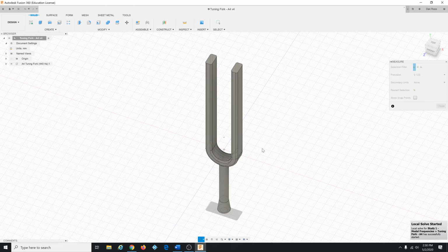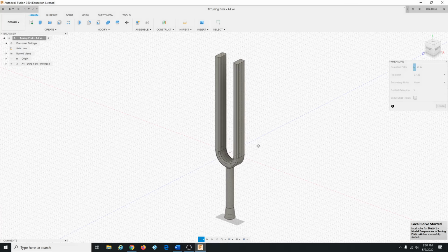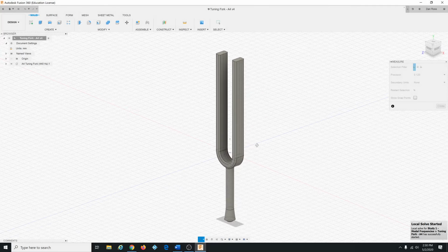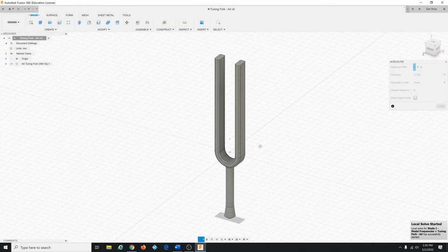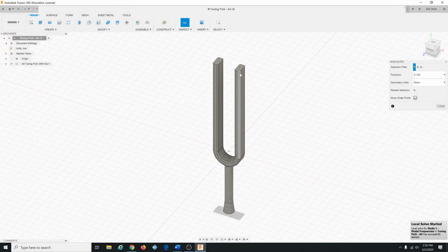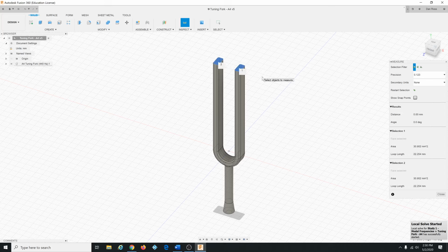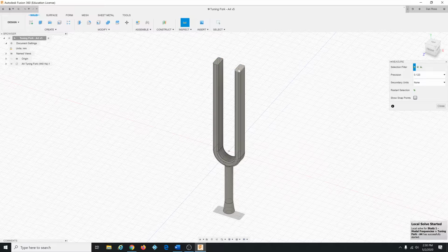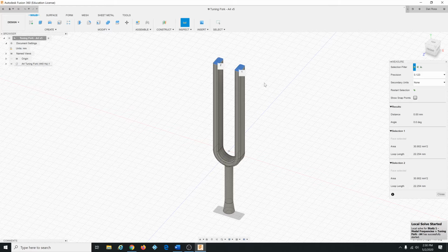All right, so this was modal vibration analysis. So a tuning fork is an obvious thing that you actually want to vibrate, but this is important for things that we don't want to vibrate, because everything has a resonant frequency. In this tuning fork, its resonant frequency is 440 hertz. But in real life, there's machinery that you often don't want to vibrate. So it's convenient or useful to solve for the resonant frequency and then check to see if you're stimulating the machine at that frequency anywhere.